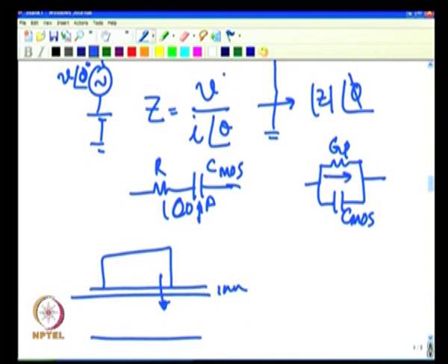So, as a user, if you have made sure that there is no series resistance, the rule of thumb is that if you are dealing with a MOS capacitor which has a reasonably thick insulator, let us say 10-20 nanometer, and you have verified by an IV measurement that there is absolutely no leakage, then you never use this model, because there is no leakage path anyway.